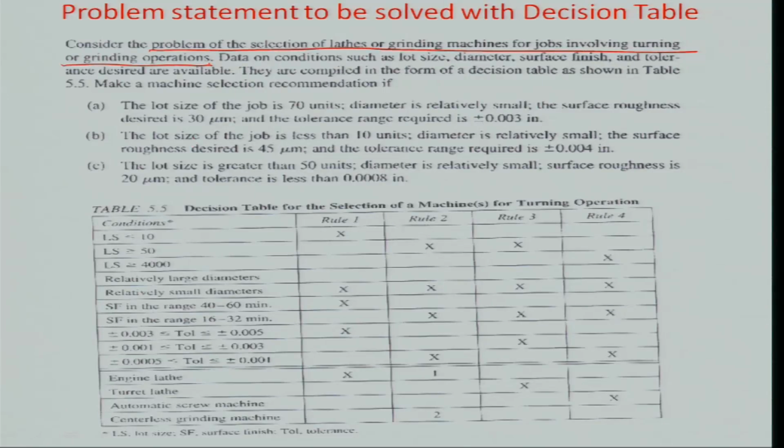What we mentioned is that in the generative CAPP process, the operator knowledge would somehow be recorded in the process plan. So it is one step advantage over the variant CAPP, in that whatever is the hands-on experience of all operators and manufacturing professionals already working in a process would get updated as process knowledge in the plan, and it is one of the reasons why such decision tables need to be made. So you look at this example.